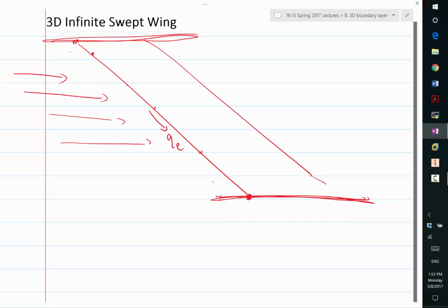It's very positive, right? So if you go slightly above the leading edge, the velocity goes towards the upper surface. If you go slightly below the leading edge, the velocity goes towards the lower surface. So there is high divergence here of the streamlines. If you look here, the streamlines are going like this, right? And if you look underneath, it'll be the same.